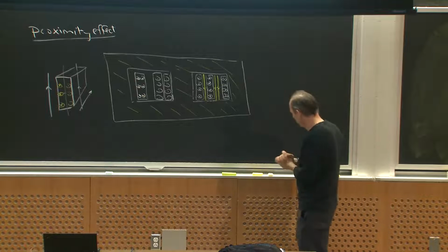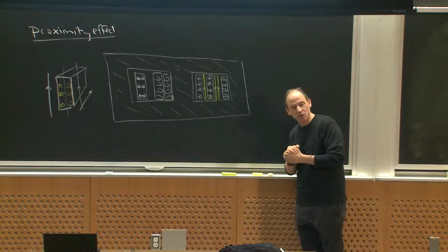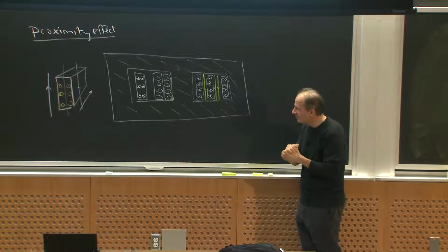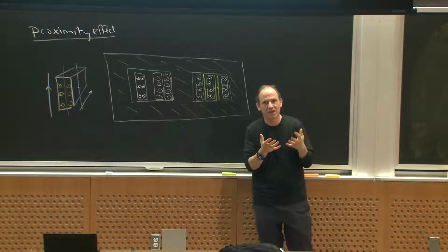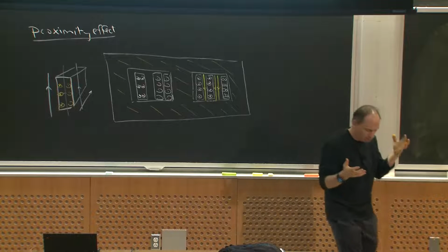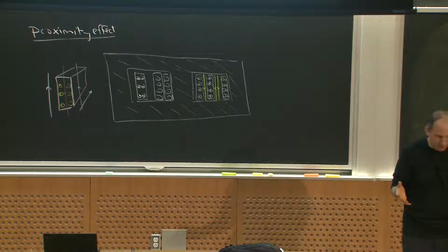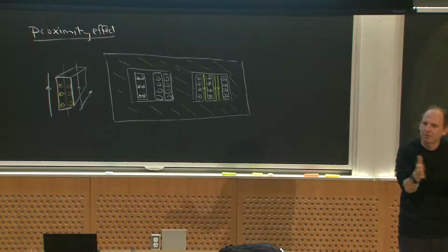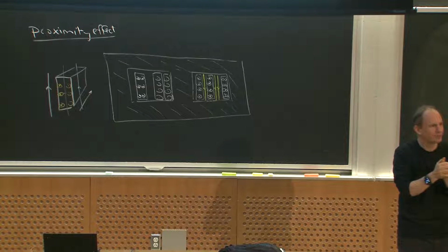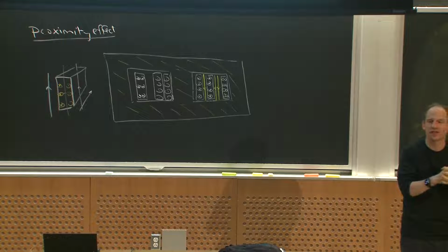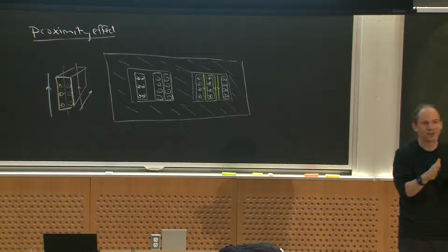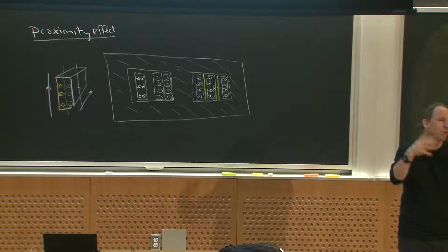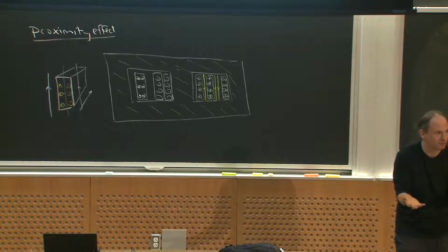And in fact, what does that say you should do? Typically, if I said, okay, because of skin effect, I wanted my wire to be on the order of a skin depth or thicker, or at least my strand diameter for my litz wire. If you include proximity effect, very often you want your strand diameter or your wire diameter to be maybe 0.3 skin depths, right?